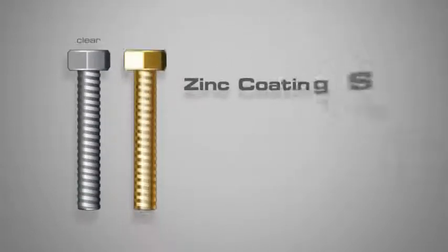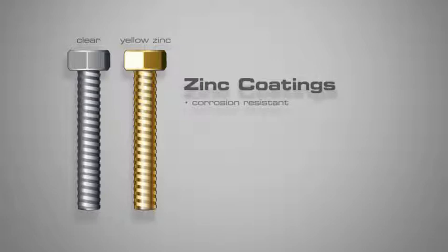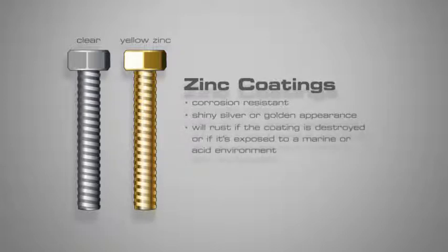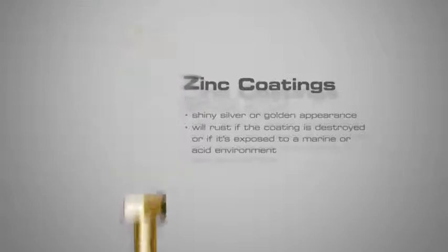Different fastener coatings are used for different applications. Many steel fasteners are electroplated with zinc for better corrosion resistance. Fasteners with a zinc plating will have a shiny silver or golden appearance referred to as clear or yellow zinc respectively. Zinc plating is fairly corrosion resistant, but will rust if the coating is destroyed or if it is exposed to a marine or acid environment.